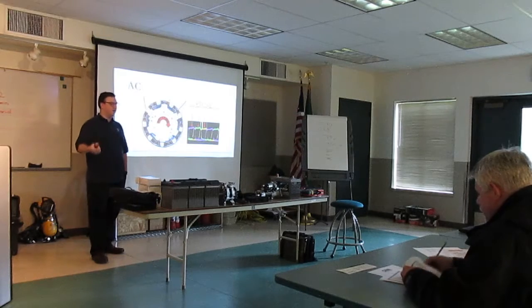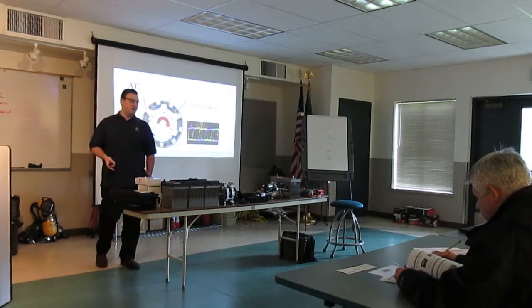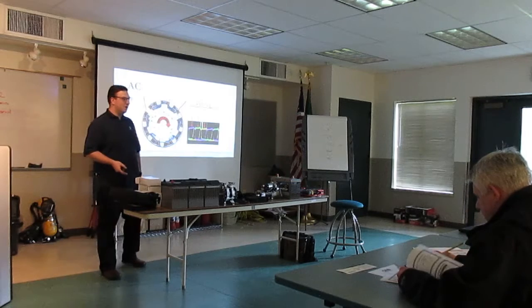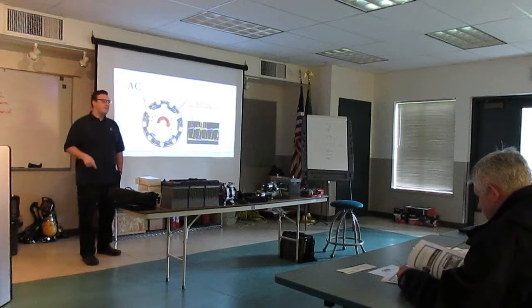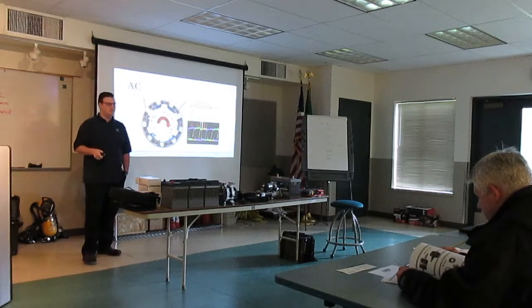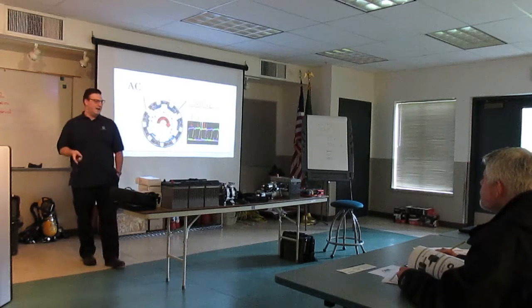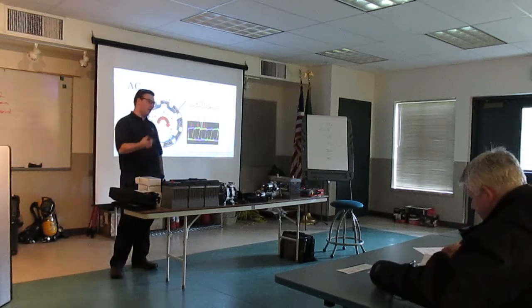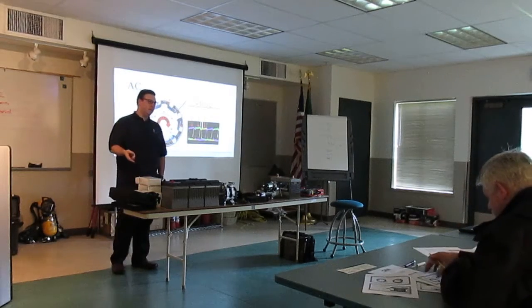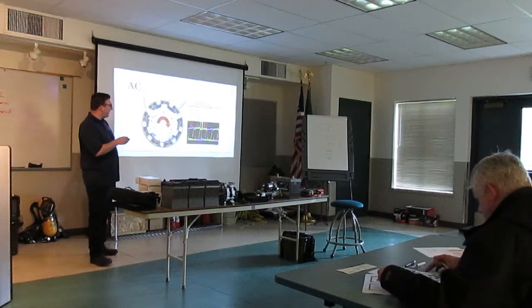What you're looking for whenever you're looking at ripple, if you have somebody that has an oscilloscope and wants to show it off, they bought the $4,000 Matco or Snap-on Modus, and let me go hook this up and show you the ripple. Oh, look at this. No good pattern recognition. Whenever you're dealing with an oscilloscope, on any pattern, but especially on ripple, it's known pattern recognition that you're going to see. And for ripple, it's repeated pattern.